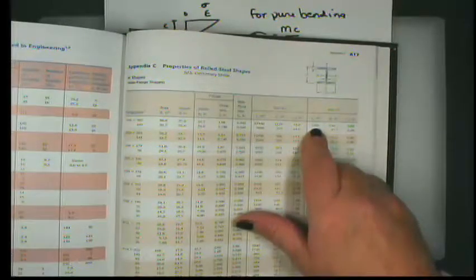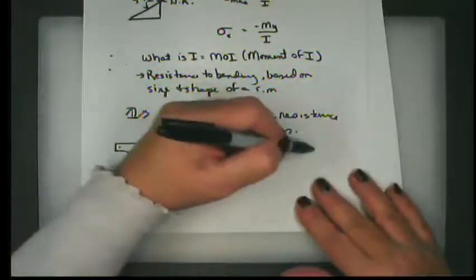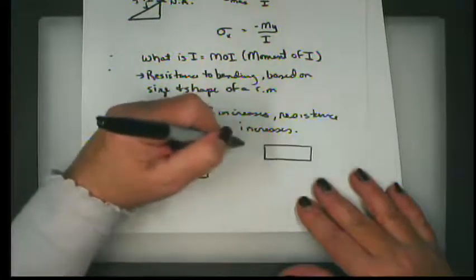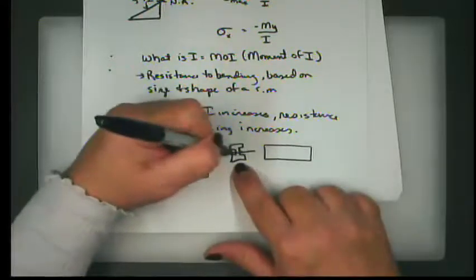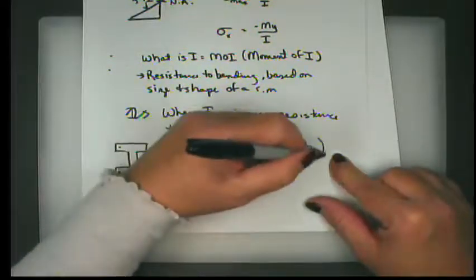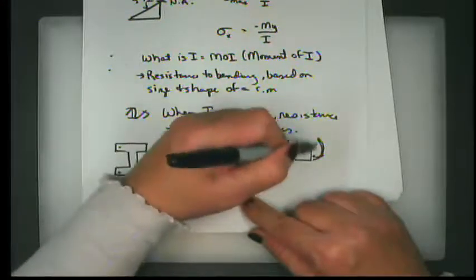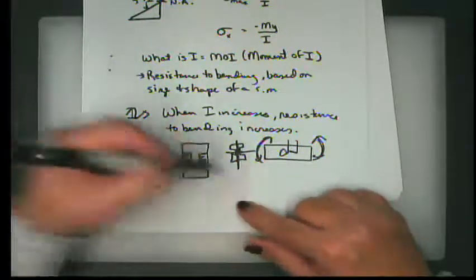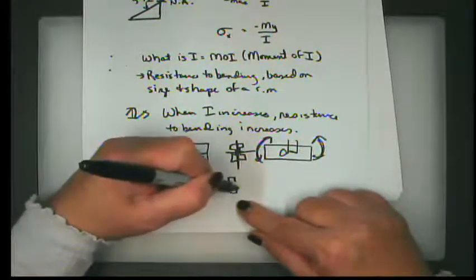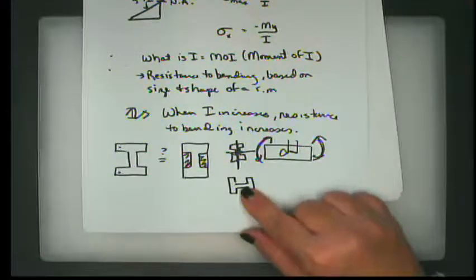compared to the Y-axis. So in other words, when you build something with an I-beam, like a bridge, you want the sides of the bridge to be like this, because the bridge wants to bend in this direction. When you load it, it actually bends like this, flexes in this way. So you need to have that resistance to bending in this direction. If you laid the I-beams like this, that would be a terrible use of an I-beam. That would not resist bending in the same way.